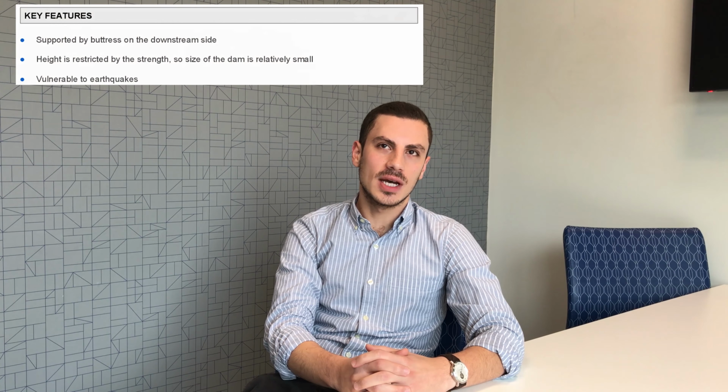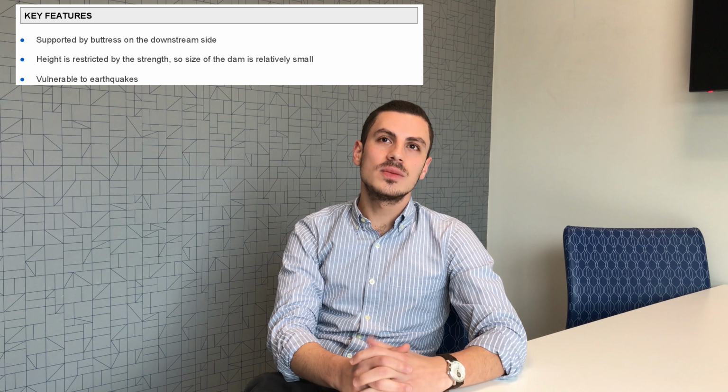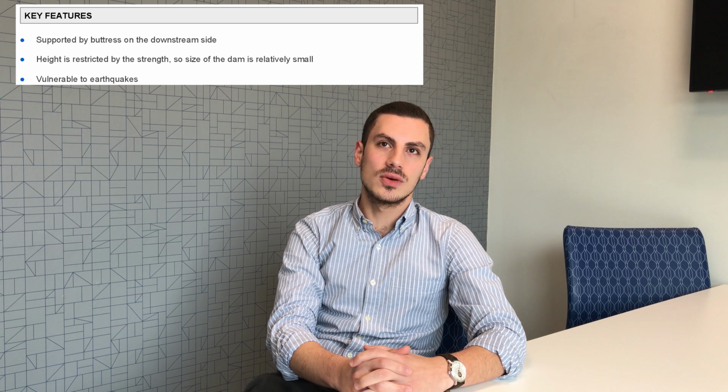previous layer finishes. Buttress dams are a type of gravity dams, and what's unique about them is the presence of buttresses on the downstream side to provide support. The construction process and lessons learned are similar to those of gravity dams, with few variations. For example, we can construct buttress dams on weaker foundations with thinner sections and thereby use less concrete. However, that leads to the dams being more susceptible to damage, and the saving in concrete costs is often offset by the cost of formwork and reinforcement needed to build the buttress system.